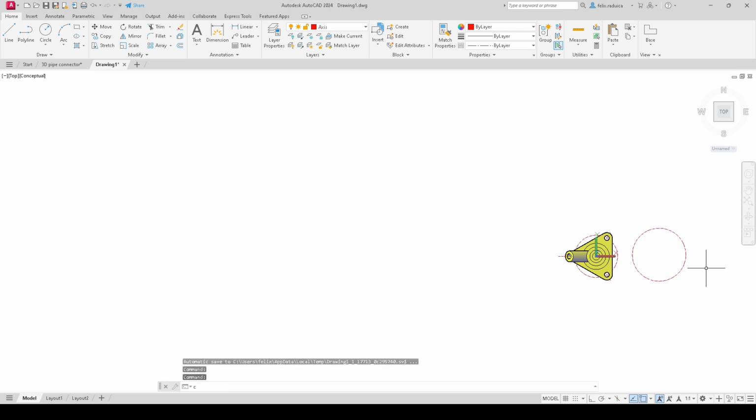So we'll create a circle, and we'll say first we'll draw a helping line. So let's draw a helping line from the center of this circle here towards the right. So at 30, comma 0, and this is the point where we need to start the other circle.